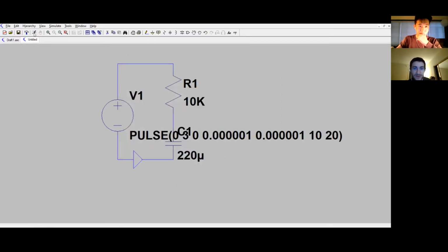So these actual parameters, T rise and T fall, are basically the rise and fall time of the on and off cycles. So basically when it goes from 0 to your V on voltage, it's how long it takes to get there. Depending on what type of wave you want, you might want to change that. If you end up putting 0 in there, it doesn't actually make it 0. It will default to a linear transition between your V initial and your V on. I'm not exactly sure what it decides as the slope, but it's more triangular than a square wave.